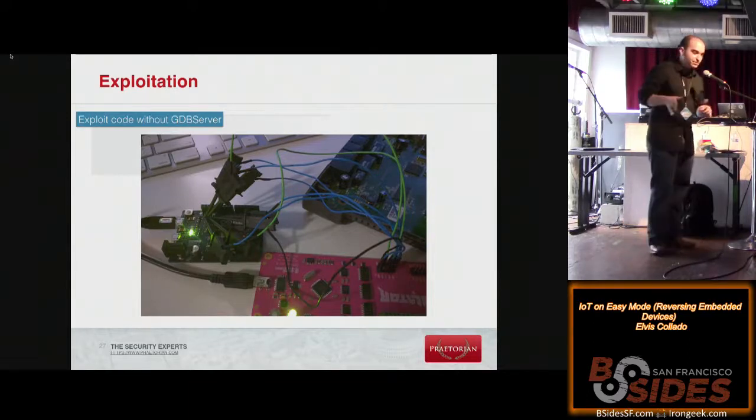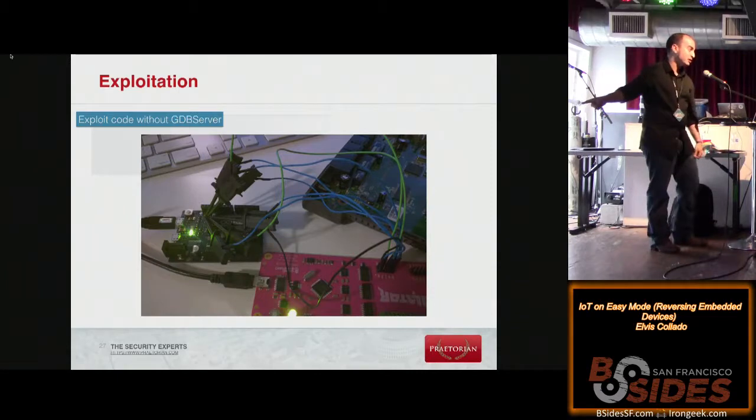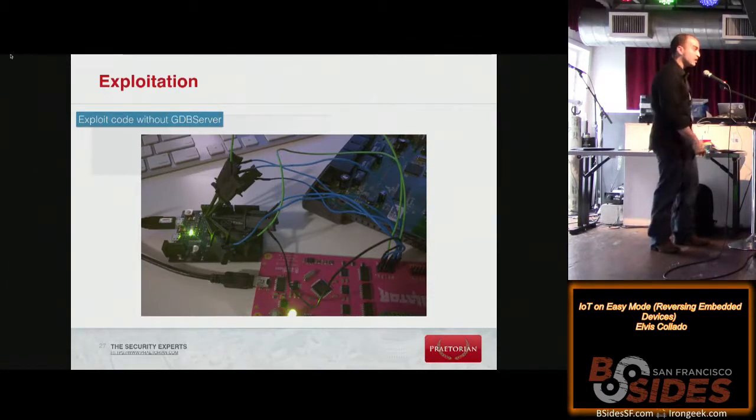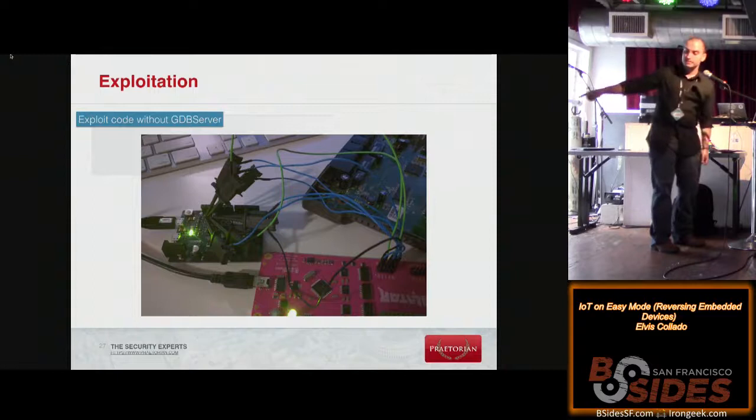So I'm also creating some vulnerable applications for this thing as well, so it forces you to use JTAG. So you have to start using JTAG in order to create your exploits. And if you do this, you will be able to do it on actual devices going forward. This is the JTAGulator as well.